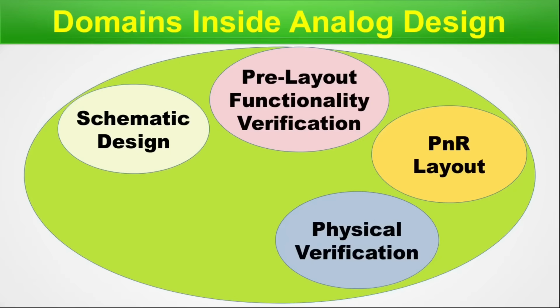This is because once the layout is ready, we cannot really differentiate it from the layout coming from the digital. In layout, everything is in terms of diffusion region, wells, poly, several metal layers, via interconnect, etc. So the physical verification is done using tools like Calibre DRC, PVS, ICV, etc. The layout is made clean of DRC and LVS errors. Then the DSPF is extracted using the StarRC tool. Using this DSPF, EM and IR violations are detected and corresponding rectification is done by going back into the layout.